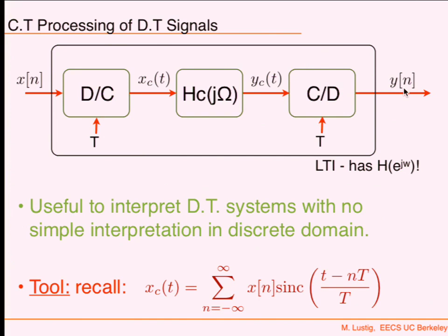Now, the interesting thing is that if this is LTI, it's always LTI. Because there's no aliasing here. There cannot be aliasing here. Let's see if there could be aliasing. You go from here to here, this is band limited. This doesn't generate new frequencies because it's linear shift invariant. I sample a band limited signal. LTI. Okay? It's always LTI.